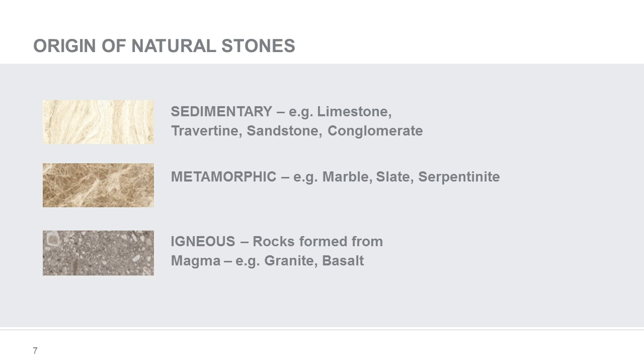Igneous rocks are rocks formed from molten rock. An example is granite. It contains approximately 60% feldspar, 30% quartz, and 10% mica. It's the mica which leads us to take additional considerations with natural stone due to its tendency to discolor. Granite is a great option for kitchens and bathrooms due to its antibacterial qualities.